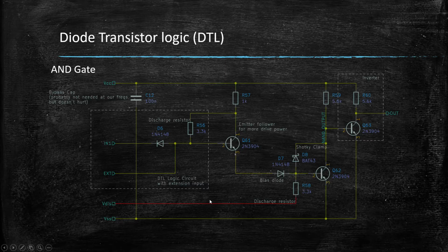Just an FYI, you need to be a little bit careful here because the base emitter junction usually has a fairly low breakdown voltage. The transistor we are using, the 2N3904, and we'll go into why we are using that transistor particularly in the next episode, has a base emitter breakdown voltage of 6 volts. So if we exceed that voltage here, then nothing good happens and our transistor might die, because it's not built for actually having current flow in reverse over our base emitter diode junction.